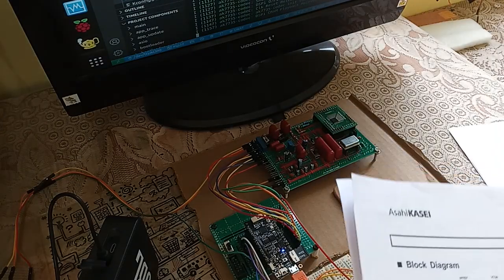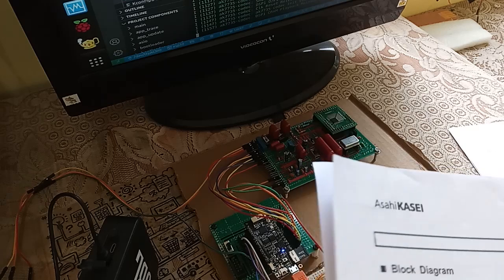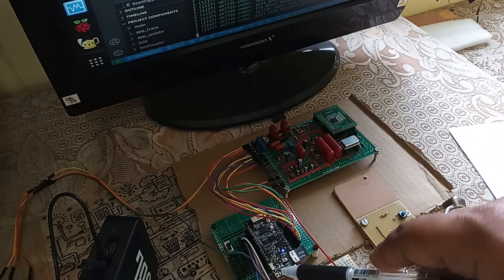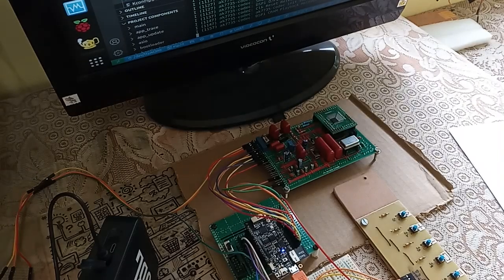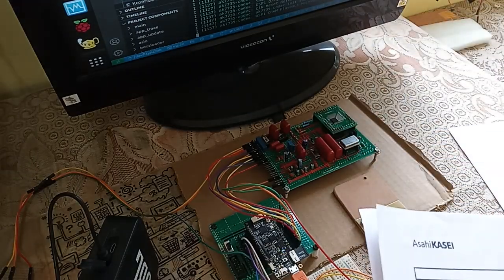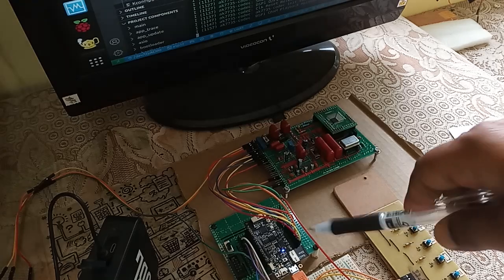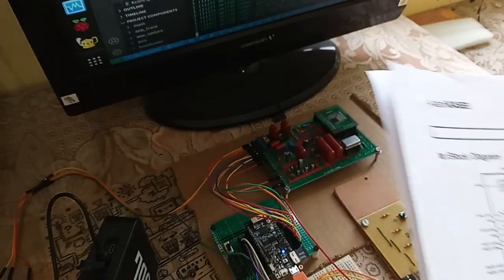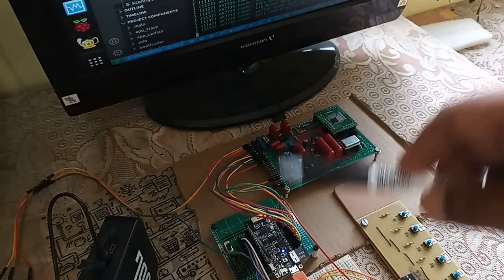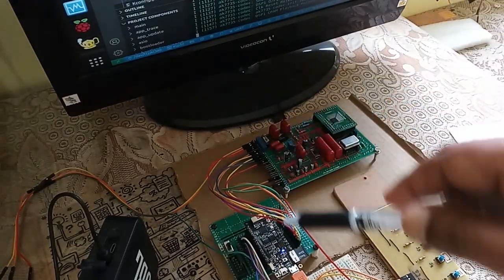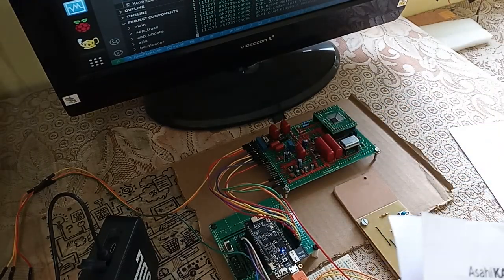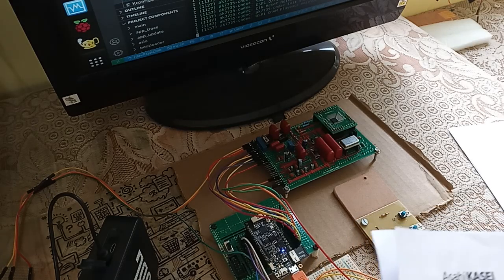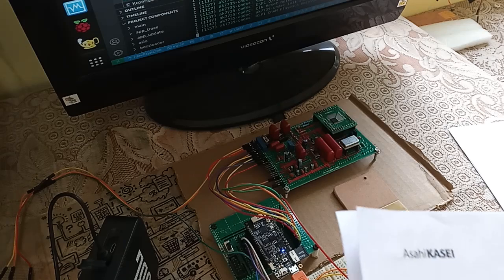Using DMA over I2S, we read the audio file and transfer the data over the I2S buffer on DMA to the I2S channel of this ESP32, which is fed to the AK7735. The sampling frequency is 48 kilohertz for the playback, with the bit clock at 1.536 megahertz and the master clock at 12.288 megahertz.